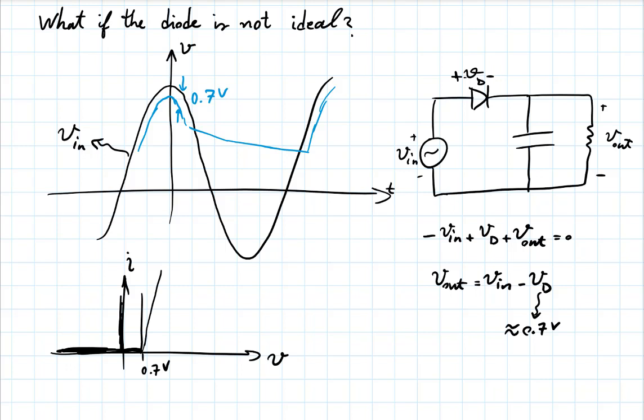The difference between input and output will be changing throughout that conduction region. It will go maybe somewhere between 0.65 and 0.73, just to throw some numbers. Because the diode current is changing as you charge this capacitor at different rates. And so the voltage that it will take, according to this, if the current is changing, well, the voltage is also changing a little bit.